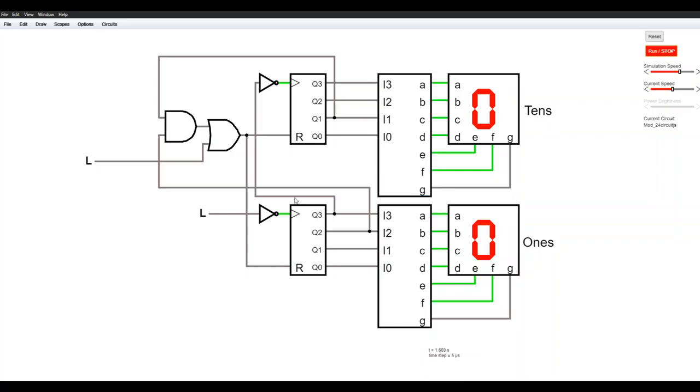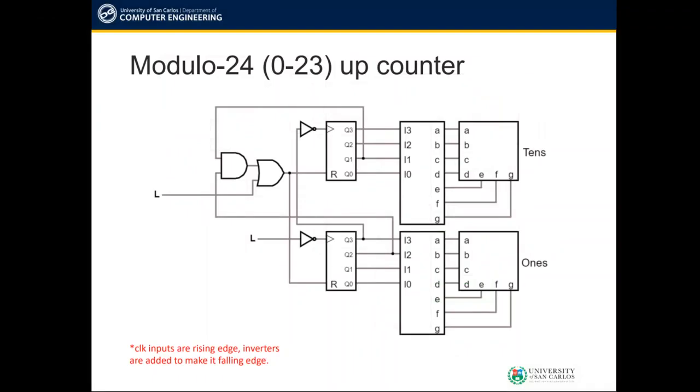As you observe here, I'm using the 3 value instead of 4. So the difference between this one and the previous example is that we are controlling the clock. That's from high to low. So remember, what we want here is the condition high to low. So from 23, the transition from 23 to 24, that's the time it goes back to 0.